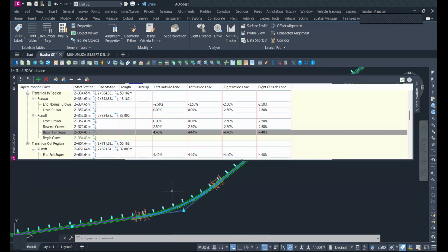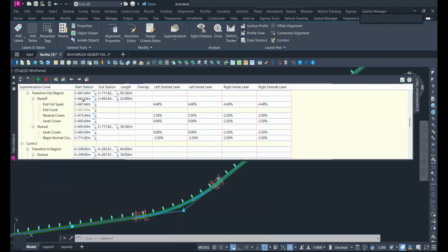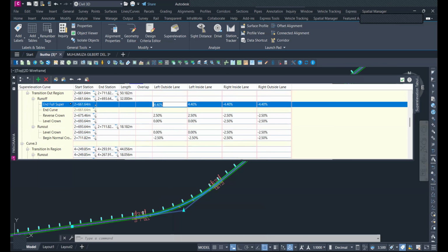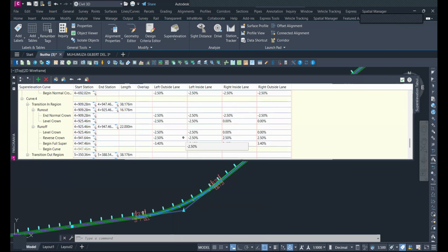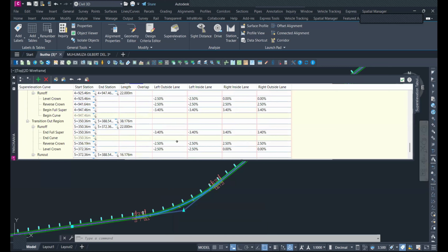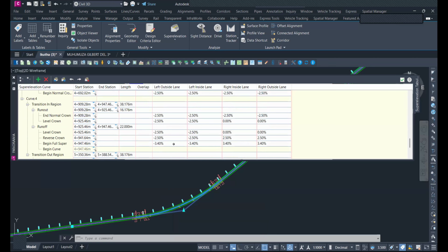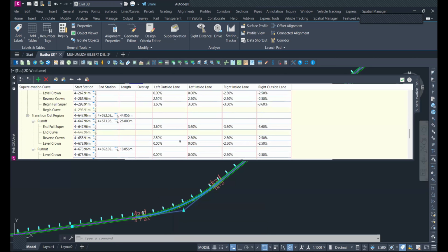I like that. So this super elevation report, you can explore it. For example, you can see the super elevation for this section is going all the way to 4.40%, and 2.5, and all of this. So it looks like I have not been able to violate any AASHTO rules or the manual specification rules, and therefore my design will be good. That does not mean that it is practical. You notice that there are some small errors that you can fix going forward.